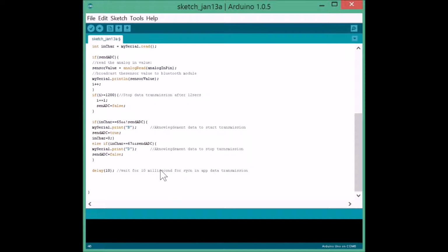Also please note that this tells us the sampling rate. Sampling rate means the interval at which we are taking the read values. For example, we have analog data at the receiving end, and we can only transmit digital data over a Bluetooth transmission, right? So we need to change that analog ADC value to a digital value, but we can do this only for discrete time intervals, right? So we'll be doing it every 10 milliseconds. So this also specifies the sampling rate of our data.